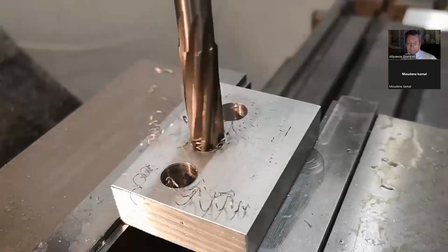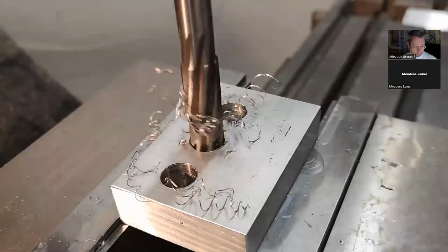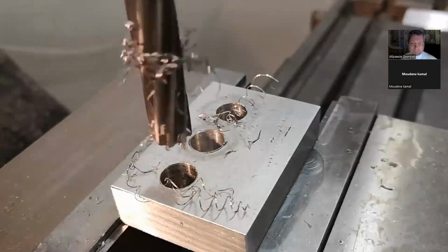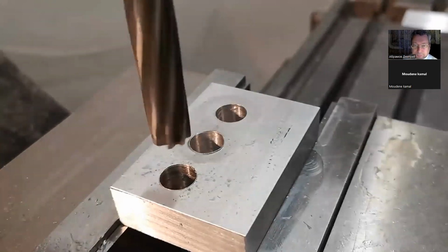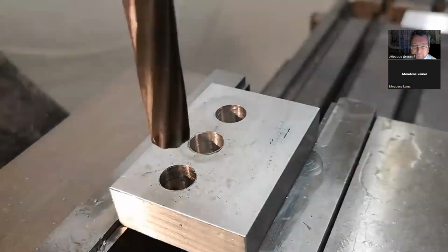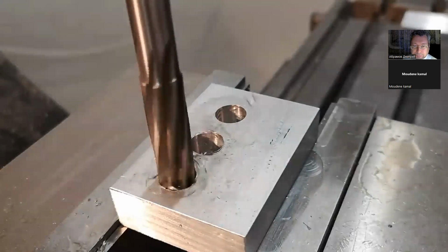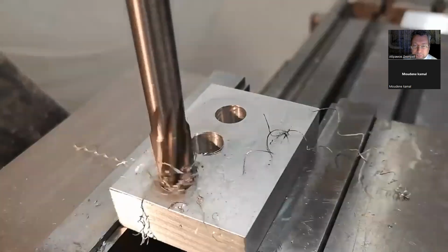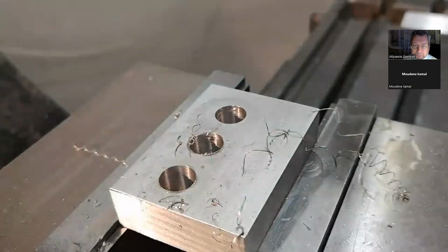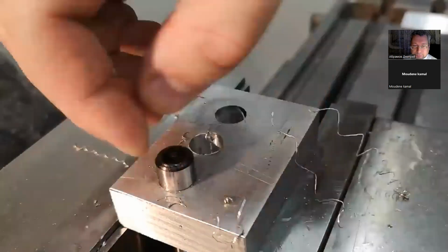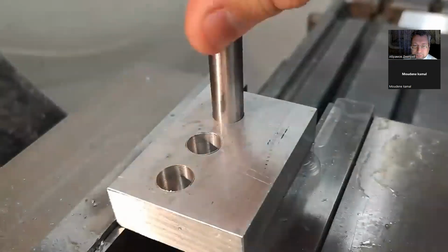So if we want a dowel pin to fit loosely in a hole, we measure it, we ream the hole to have a little extra space in it, and we put it in. The problem arises when you have a bag of 100 dowel pins and you have to ream 100 holes. Dowel pins have a tolerance on them, and their sizes will always vary a bit. Your reamer will also cut slightly different sized holes, depending on your work holding, wear in the reamer, and the cutting parameters, all of which can change while reaming your 100 holes. Because you bought the dowel pins and have no control over their tolerance, this is called a shaft basis fit.